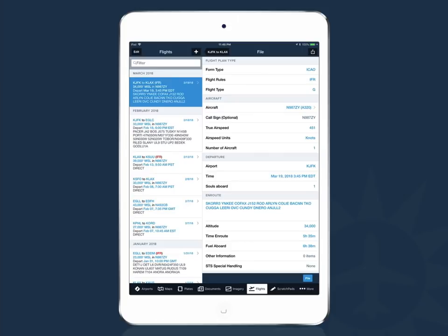You should become familiar with how to file with ICAO. And the reason is the FAA is transitioning to the ICAO flight plan format in the near future, and the FAA domestic form is going to go away. So make sure you change that to ICAO. And if you have questions on what the differences are and that sort of thing, you can check out our filing guide. It's on our website. It's also in that document catalog I talked about where I downloaded the manual. You can look at the filing guide in that view as well.